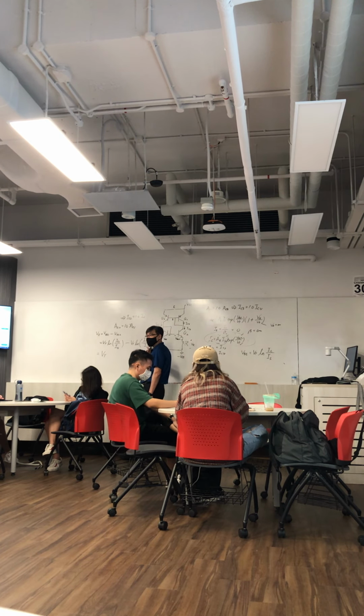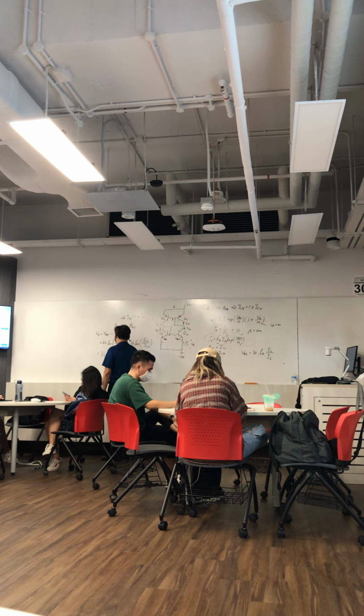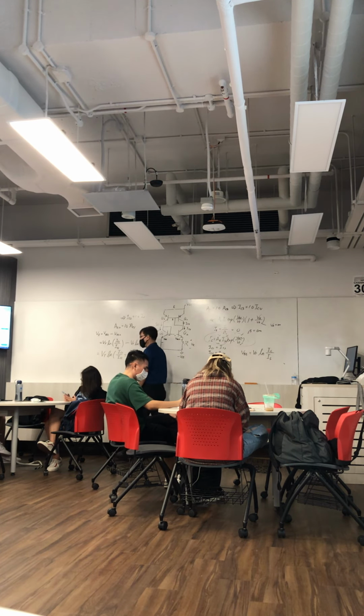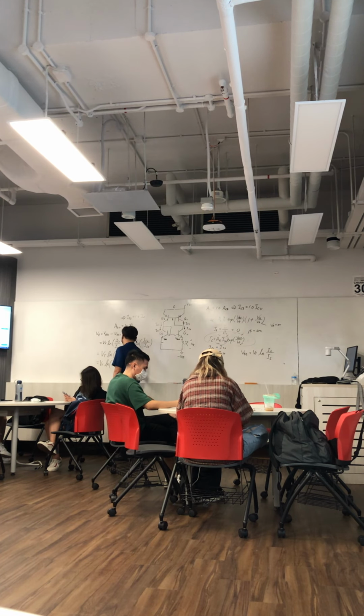Log A minus log B is log A divided by B, am I right? So then I will have log of IC1 over IS1 divided by IC2 over IS2. Alright? So this will give me VT log of IC1 over IC2, times IS2 over IS1.